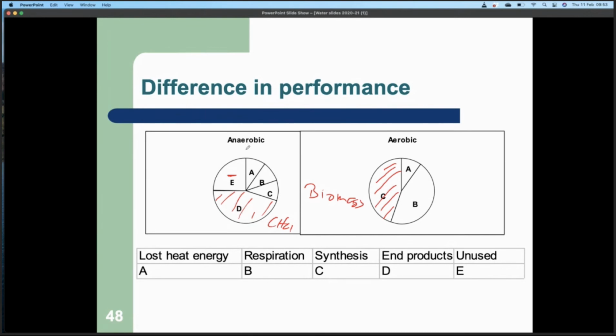So again, anaerobic digestion is much better in terms of carbon balance, but it's fickle, it's tricky, not easy to run. It needs continuous or constant conditions. Not good for dealing with change. Aerobic treatment is not very energy efficient. It gives you a secondary problem of lots of biomass, but it gives you really good removal rates, and it's stable. And that's why aerobic treatment is used in secondary treatment, and anaerobic treatment is used in sludge treatment.